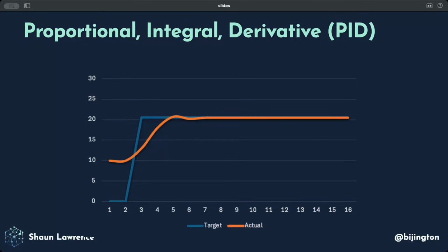And what happens once we apply this algorithm, you will then see that you can achieve a much smoother ascent, and that you will always overshoot and undershoot slightly, but you will then be able to account for errors and actually ideally create that flat line there. Now, of course, there will always be bumps in the road, such as someone opening the fridge door to check that the beer is still happy, but we can adjust for that and handle that and then reascend to the target temperature.